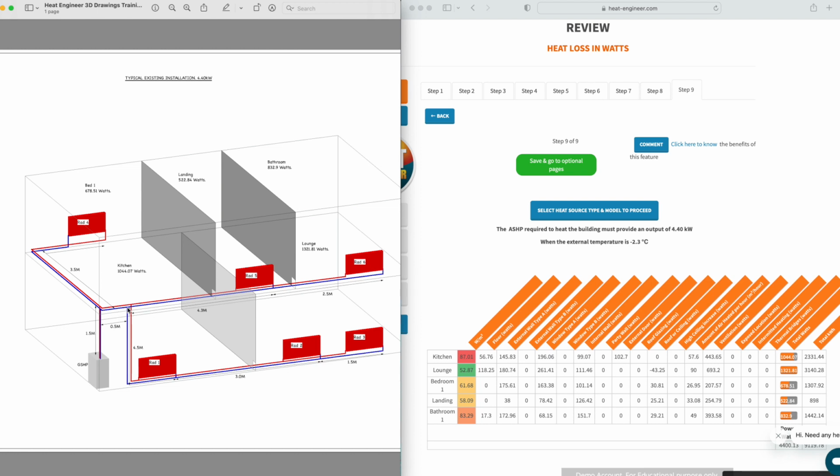So I know that I can walk about a meter in a pace, so I'll just pace that out. So that's four and a bit meters between that point there, that T section there. There's a drop coming downstairs, so I know there's a T piece there. I can see there was a bit of 22 mil pipe coming out of there, or a bit of 15 mil pipe coming out of there, running to those 3 rads, and you can just pace it out and see what you're going on. You can see radiator pipework coming out of the floors, all sorts of things like that, so you know roughly what size of pipework is going to be placed there. So as I say, all we're trying to do is get much closer to the truth.